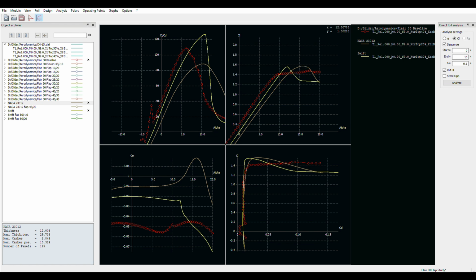You get a very distinct burble that starts here. It warns you when it's about to stall, and that allows you to avoid the stall. You get the nose back down. You get the rumble, the rumble, and you get that nose back down before you go through a full stall. And for me, on a flying wing, that's very important because that helps you stay away from a spin. Flying wings are very prone to spinning, and the best way to avoid spinning is to avoid stalling. And the best way to avoid stalling is get the nose back down before you stall. And you need some kind of warning for that.